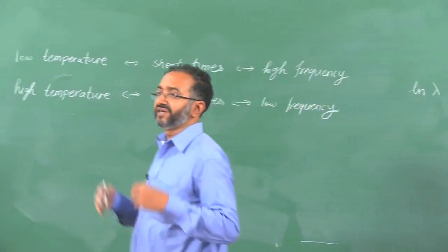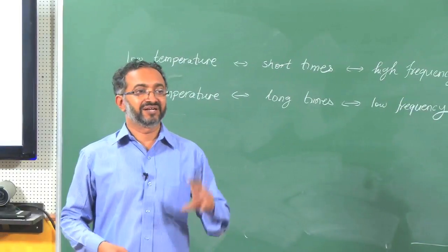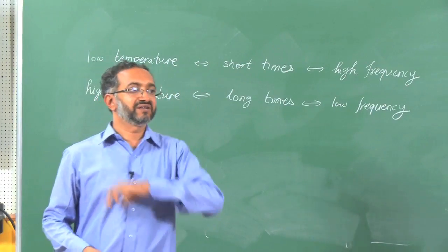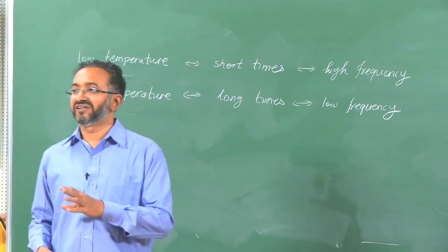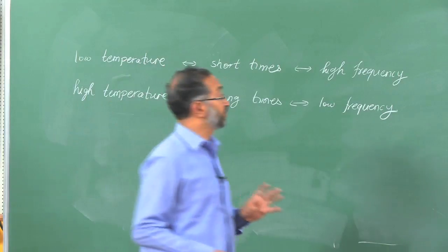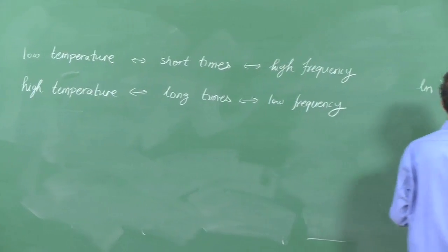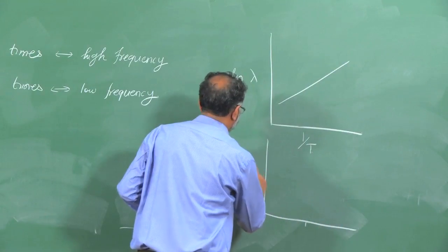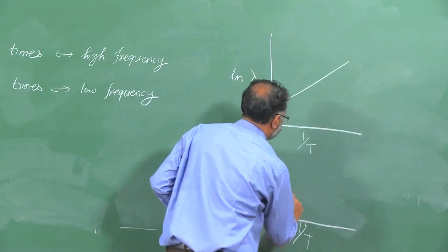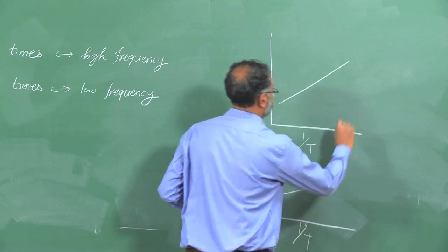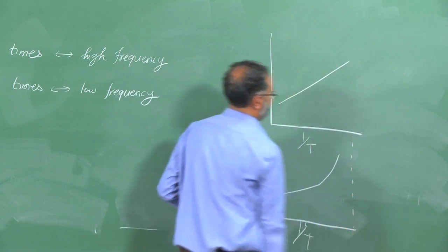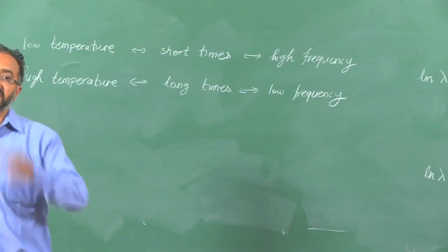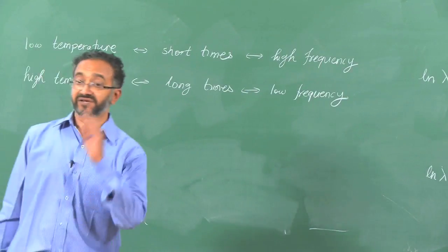That is how the idea of an activated process will be, that there is sufficient thermal energy for the activation barrier to cross, and this activation barrier will not be crossed only when you reach 0 thermal energy, which is 0 temperature. But for many materials, when you are approaching the glass transition temperature, the overall response is where at a lot lower temperature itself lambda goes to infinity, it starts diverging.